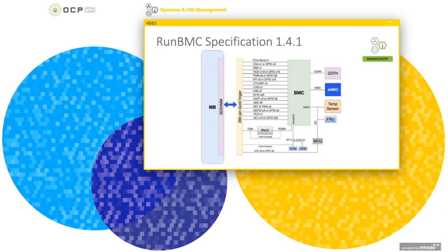As you can see in the block diagram here, the blue arrow represents the actual hardware interface between a SODIMM receptacle and a 260-pin gold finger connector. All the different I/O that's required to run a BMC subsystem is exported over the connector. The system on a module side includes the BMC, some local DRAM, and other various things that comprise the system.